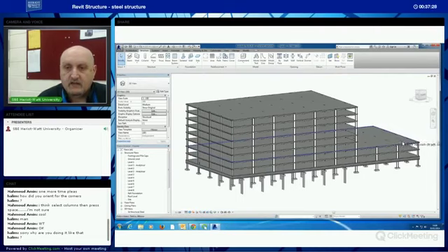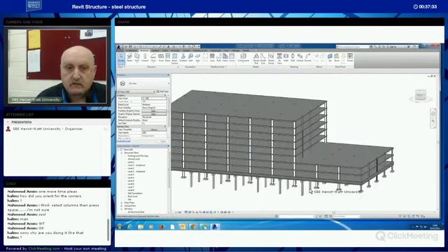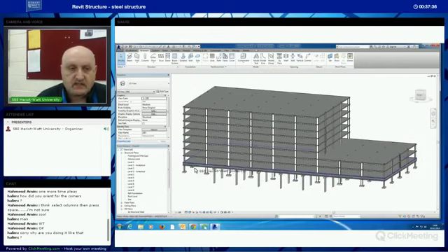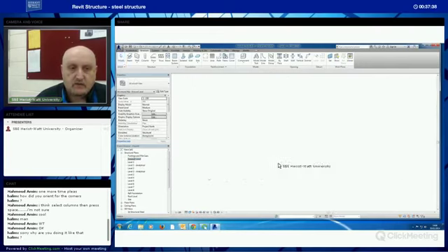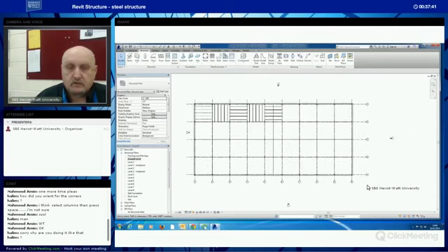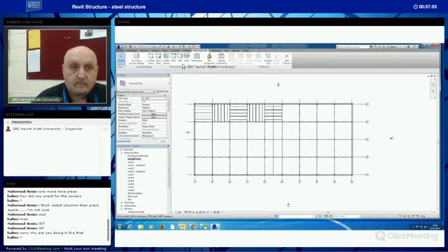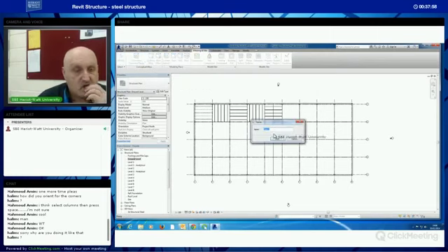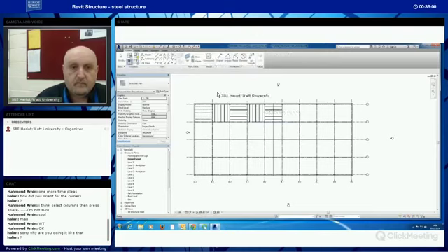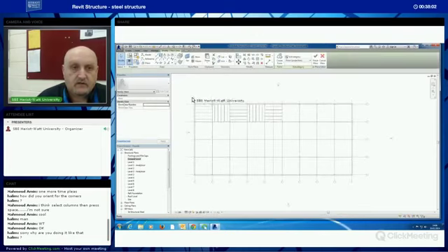And I'm going to put the massing around this part of the building and around this part of the building. Okay, massing. Massing is a tool, and it's used to put different surfaces on this kind of transparent, translucent, temporary 3D object. So I go to massing. I want to see the masses. I'm just going to use an in-place mass, and I'll use a rectangle,